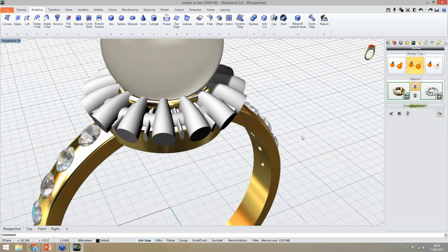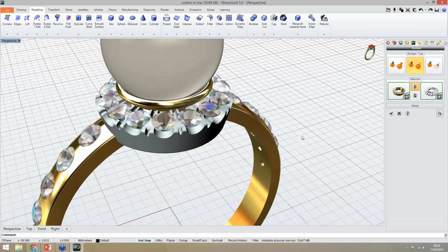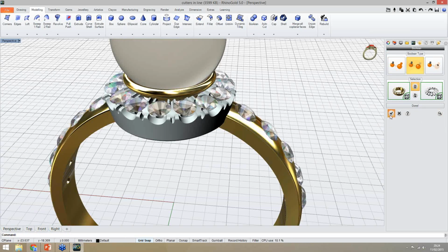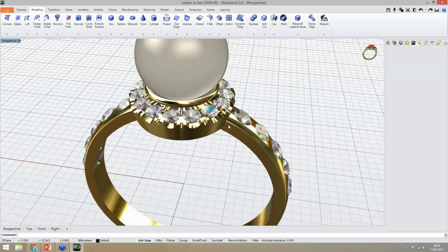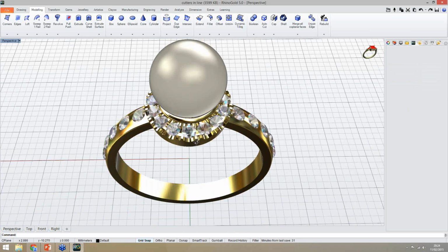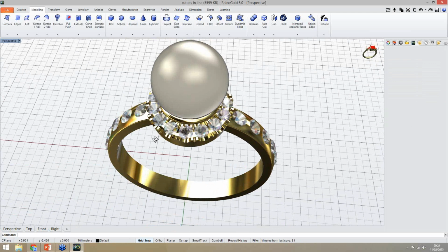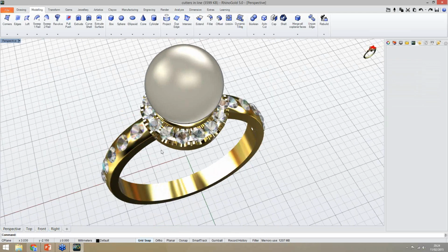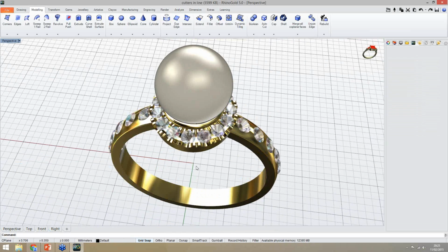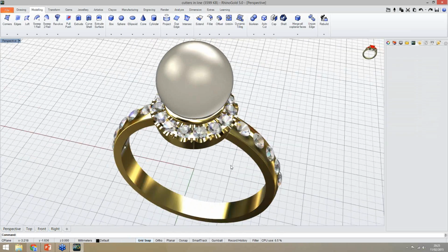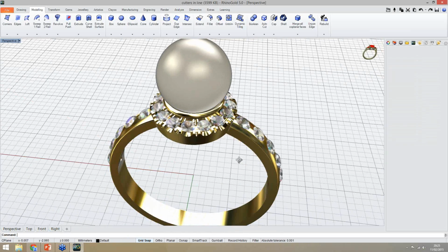At this point it's calculating the Boolean operation, and as you can see, easily I create the Boolean operation to remove the cutters, and this is the result. So this tool we had before, but now there are many more options. So the idea is to create all the cutters exactly as we need.